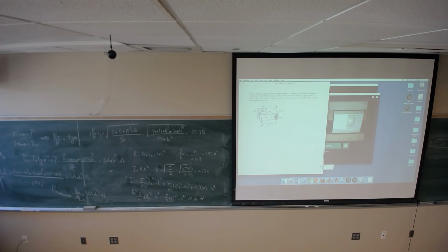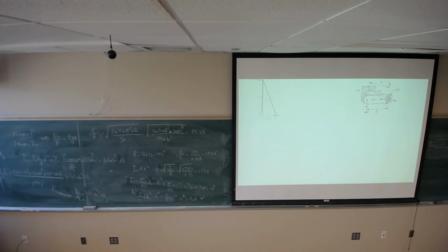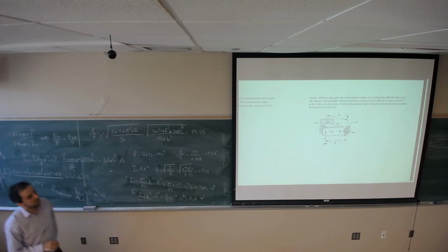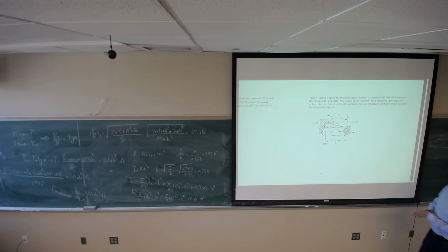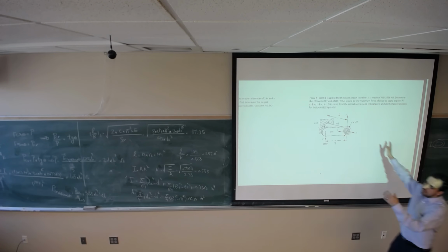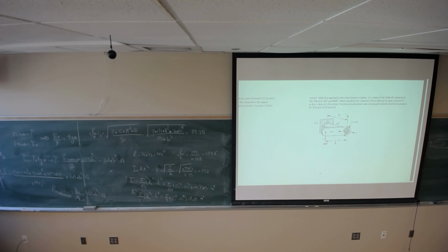And this was another problem that I gave. I'm not sure if it was last year or the year before that. One force is applied here, and we would like to find the factor of safety based on distortion energy and maximum shear stress. Again, you need to find the critical section based on the loads or stresses that these forces may create.